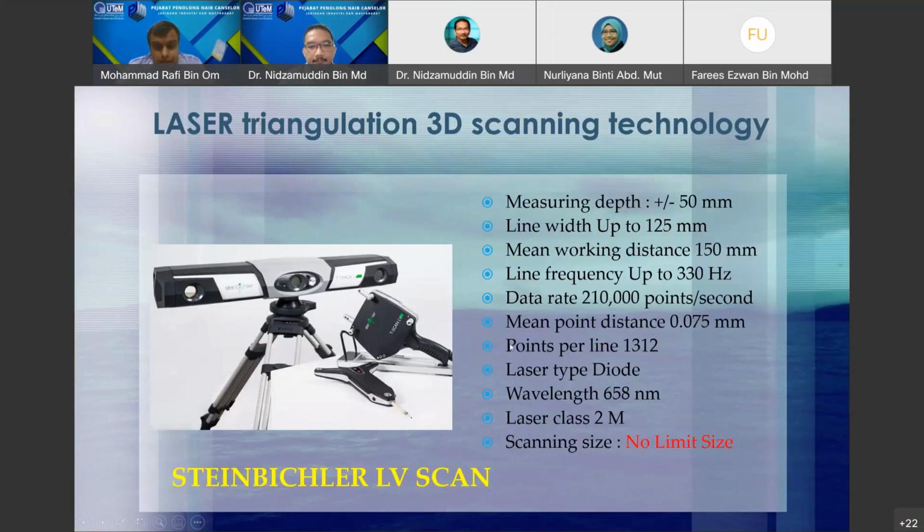Okay, this 3D scanner I showed in this video is very special because the product you scan does not need to be coated or painted. However, this scanner also has limits: when you have a transparent surface you need to coat it, and if you have a shiny surface you need to coat it. Other colors are no problem. I also created one big project using this scanner: we scanned a 12 meter hull of a catamaran boat. Maybe after this I will show you the project.